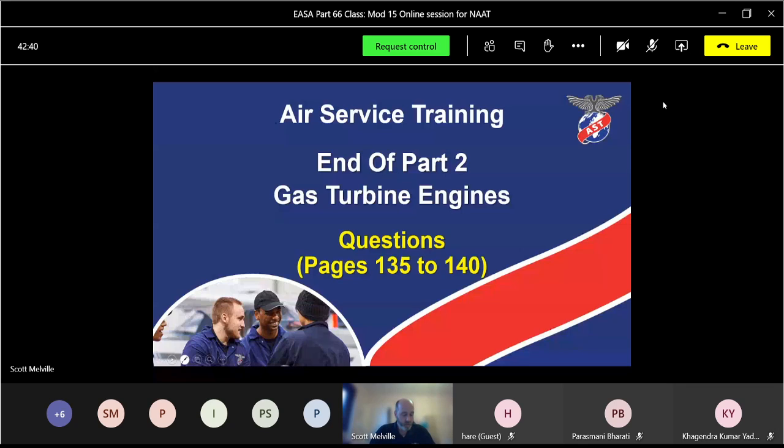So it's a closed loop circuit, isn't it? We send information out, and it gets information back in from various sensors. It could be the TLA, it could be N1, it could be EPR, it could be EGT, lots and lots of things. Yeah, good. How many FADECs are normally fitted to each engine? Two. Two, yeah.